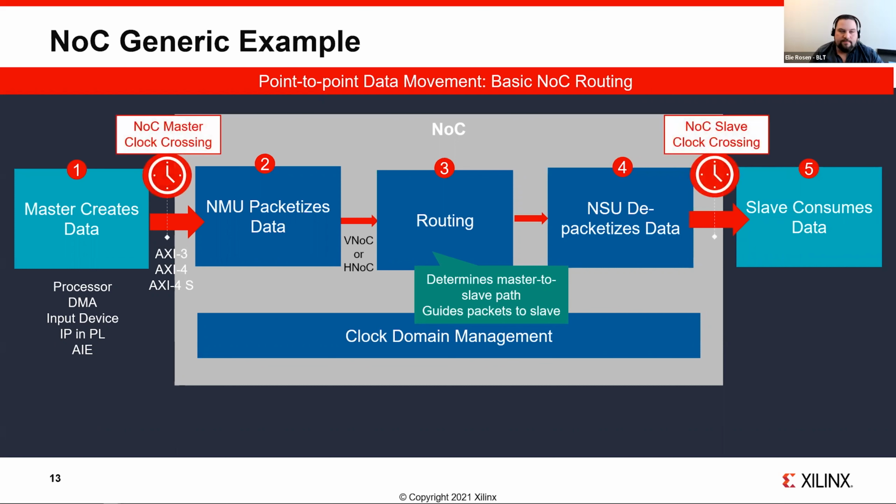Most importantly is that the NoC handles all the clock domain crossings. So as you'll see in the demo, there are a lot of clocks involved for how data gets onto the NoC and how data gets off the NoC. The key here is that inside of the NoC, data is moving with that 1 gigahertz or so clock to get data where it needs to go as quickly as possible. But then it will handle the clock domain crossing to bring that data into the relevant clock domain that you're using in your application.